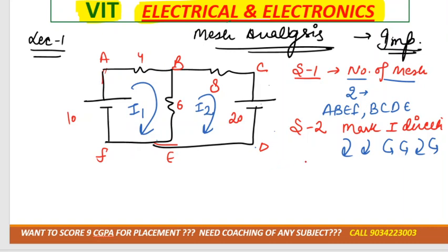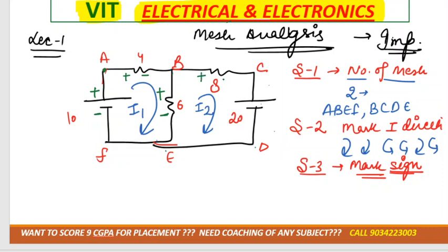Got it? Now step number 3, we have to mark the sign convention, right? As you know, current is always flowing from the positive terminal to the negative terminal. So current is moving from A to B, so it would be positive, negative. B to E, positive, negative. Battery bigger terminal is positive, smaller terminal is negative, correct? Now I2 is moving from B to C, positive, negative. Battery terminal will always be fixed, and this one would be positive, negative. Clear?